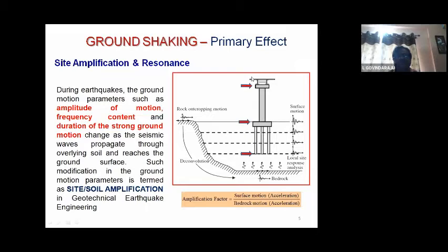At this stage, I have taken an elevated flyover or a metro, say. It is resting on what is called a pile cap, and here is a pile foundation. It is a rigid structure, reinforced concrete, embedded in a soft soil. Automatically, the ground vibrations get modified by the time they reach the ground surface. And the tendency of this earthquake is to cause inertial forces. So these inertial forces always act in the horizontal direction.